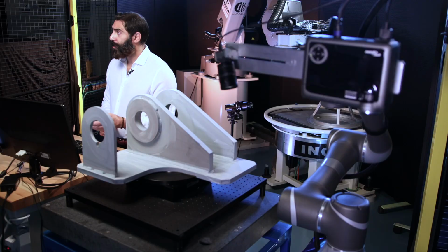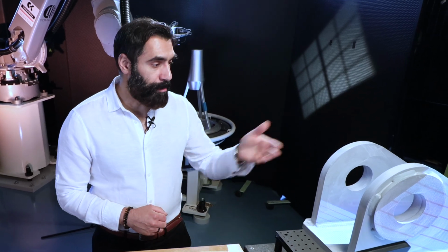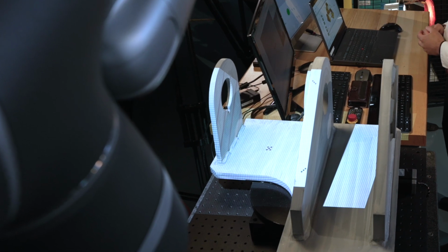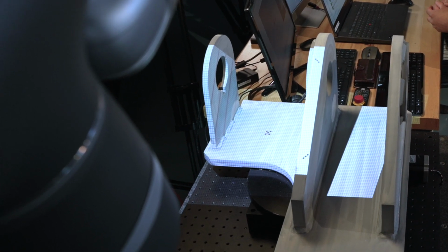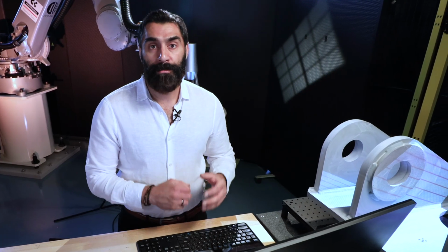Now it's time to take the scan of the part. We're going to go over to the M3DI AO software, and we're going to be using an M3DI VeriScan Flex scanner. The scanning technology is set up on a 6-axis collaborative robot, and the part is sitting on a 1-axis rotary table. So in total, we have 7 axes of manipulation on this part to be able to get to all the different surfaces we have to see to grab the information to inspect the part.